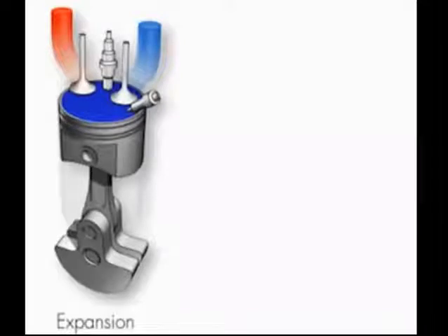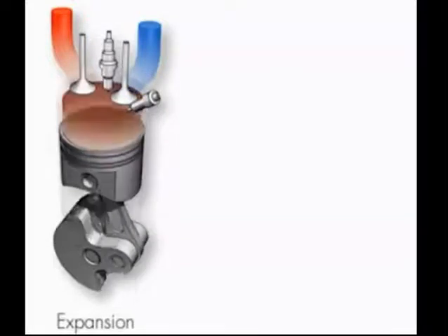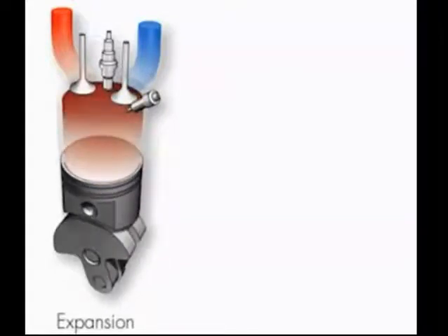The fuel is injected under pressure into the combustion chamber. On the petrol engine, combustion of the air-petrol mixture is initiated by the ignition spark of the spark plug. On the diesel engine, self-ignition occurs during direct fuel injection. The explosive combustion forces the piston downwards. The third stroke is the working stroke of the engine.